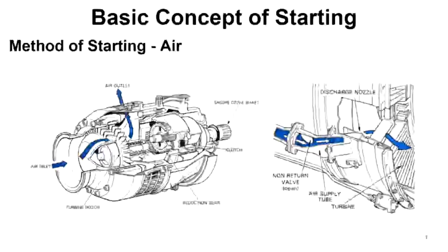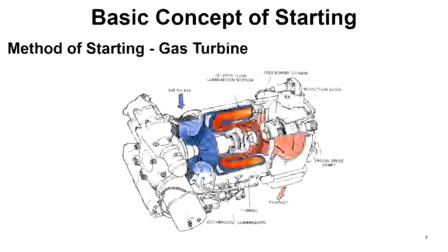The air supply to the starter is controlled by an electrically operated control and pressure reducing valve that is open when an engine start is selected and is automatically closed at a predetermined starter speed. The clutch also automatically disengages as the engine accelerates up to the idling RPM and the rotation of the starter ceases.